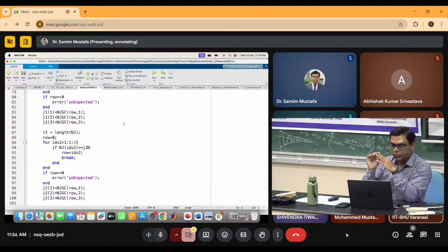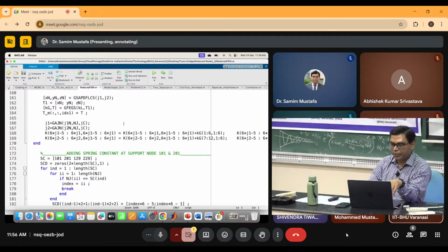And then what is the property of each member, what is the boundary condition, which one is free, which one is kind of fixed. So that way you can construct this type of K matrix, stiffness matrix, which is a very large matrix, 12 by 12 matrix for space frame. Okay, if you are coming from a civil engineering background, your K matrix for space frame means the most complex scenario will be 12 by 12. Okay,